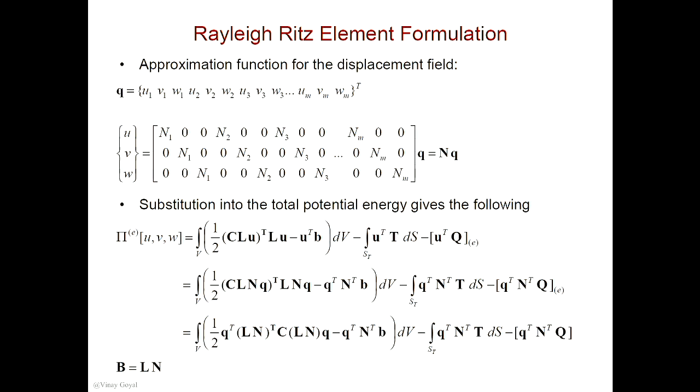For a 3D body, let's take a general situation, because you have so many different kinds of elements in 3D. It's just better to take a general situation, okay? So I could have a tetrahedron which has 4 nodes. I could have a hex which has 8 nodes. I can take a second order tet which has 10 nodes. I can take a second order hex which has either 20 nodes or 27 nodes. You can imagine how quickly this becomes very unwieldy.